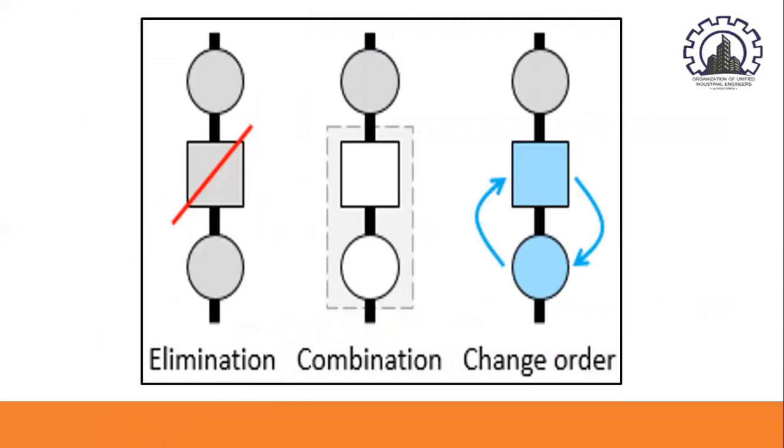All right. So how does a flow process chart work then? The typical approach is to chart the present method first, then the improvement will be proposed on a second chart. When charting for the future, each process activity is subject to elimination, combination, and sequence changing. Again, that would be elimination, combination, and sequence changing.